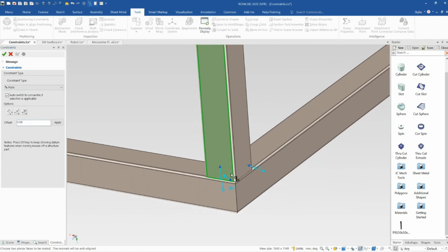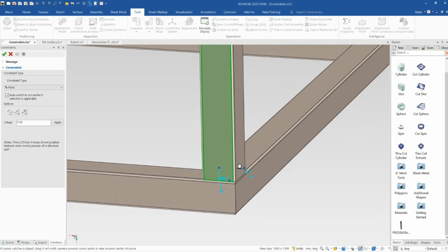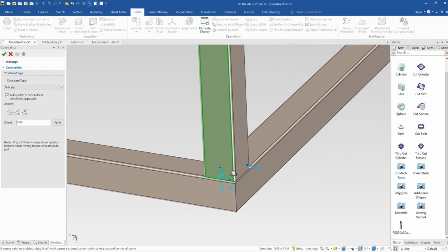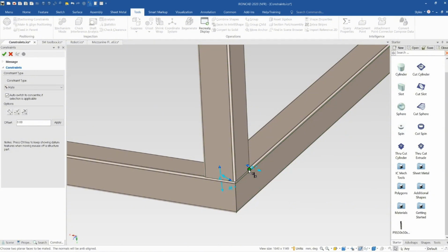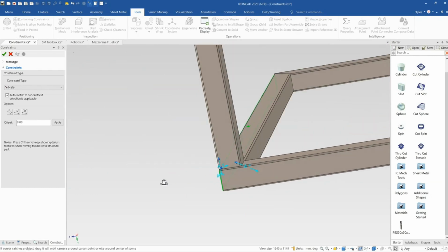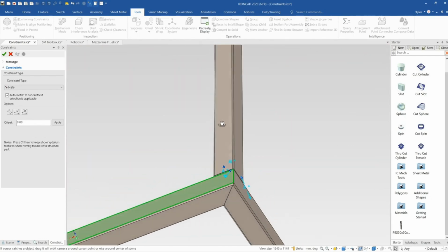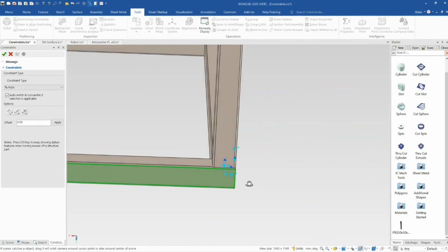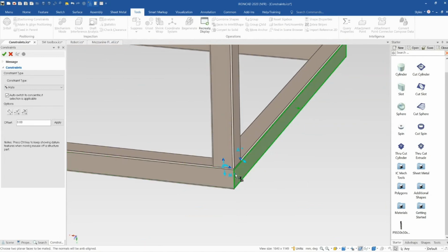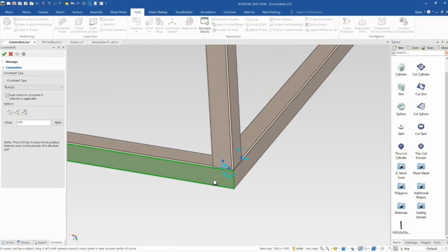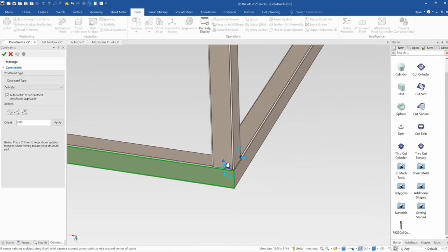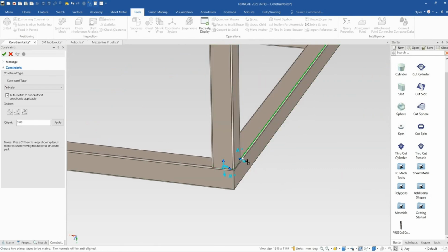It's worth noting that selecting constraints on faces is generally a good idea because it gives you very easy control of the constraint. Whereas when you're selecting on an individual point, the constraint can generally move in a lot of different directions. Whereas when you use a face-to-face constraint, it's relatively obvious the function that will be applied when you mate that or constrain that together. But of course you can also do constraints with lines and with points as well as faces. But faces are generally a good one to use, as they're very predictable in how they behave when you constrain things.